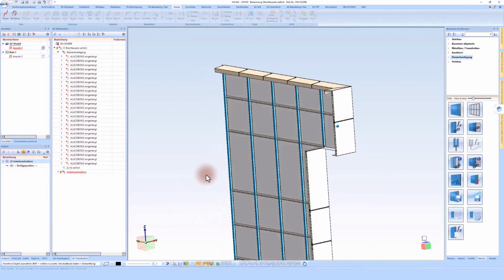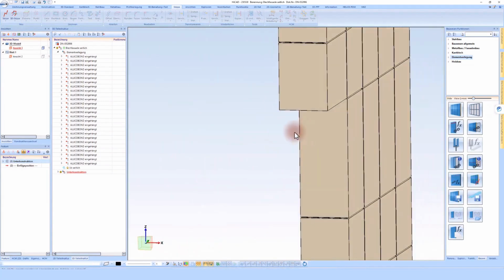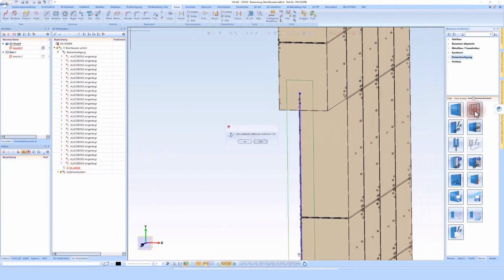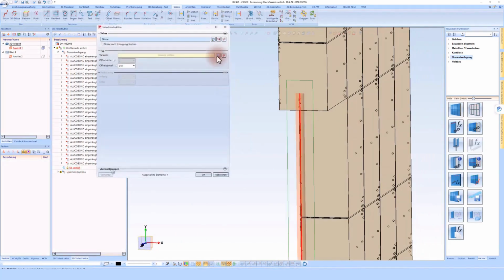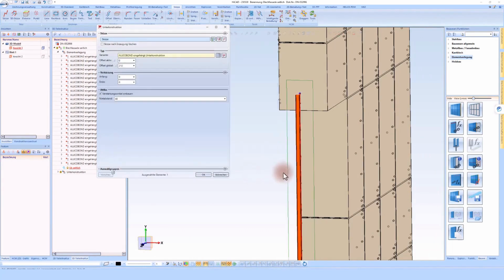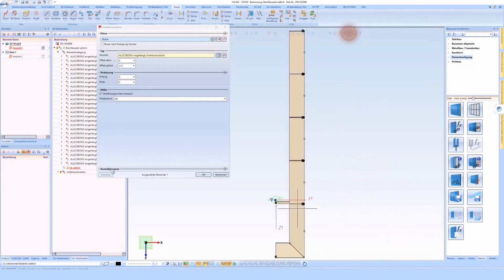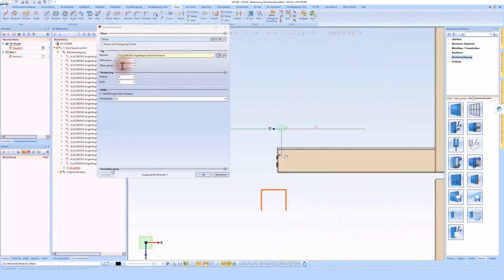So now my first profiles are correctly applied in a precise manner. I want to apply the second profile with this second sketch carefully. Again, pay attention to the position of the profile because I have a different distance here. 70 will be 75 here, and accurately. I want to delete this sketch, and by clicking OK, this area or profile will be integrated with attention to detail.